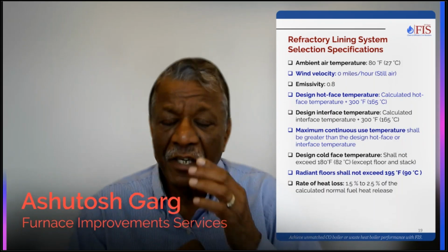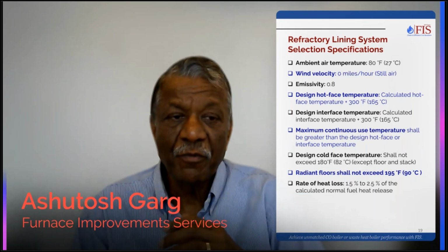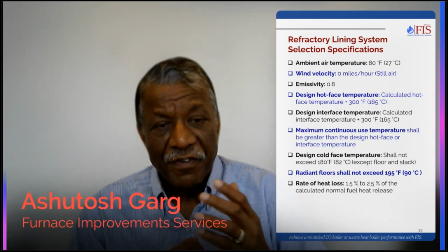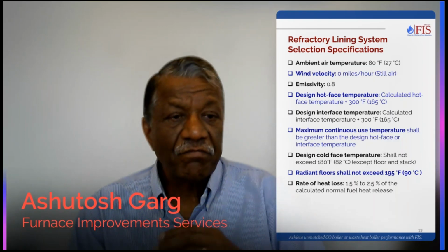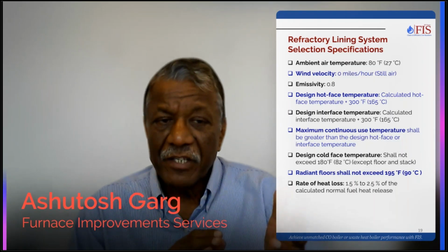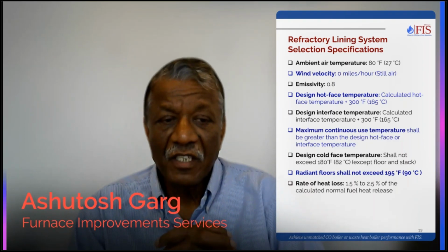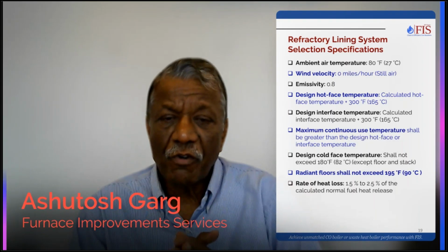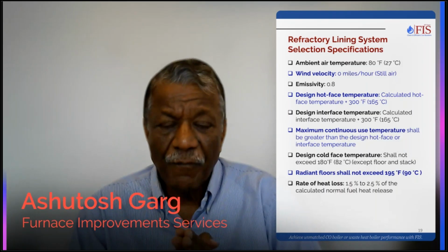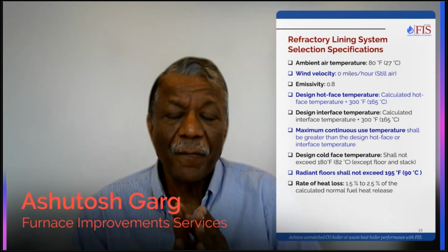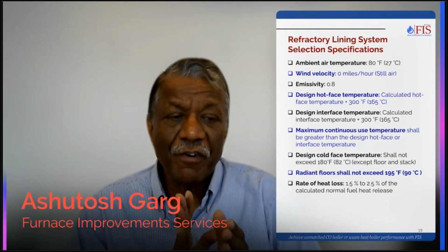Emissivity of the surface is used as 0.8. Hot face temperature is typically whatever temperature you have plus 300 degrees. Cold face temperature, what we want to control, should not go above 180 degrees. That's generally it, except for floor and stack.